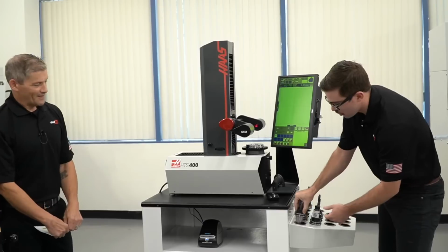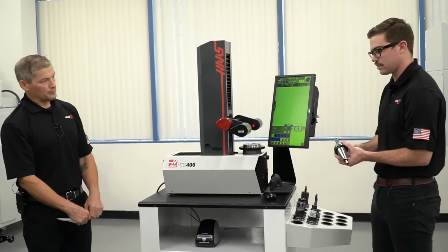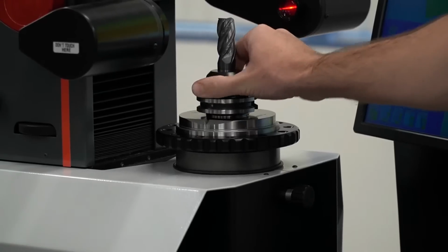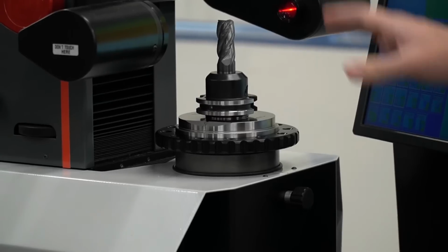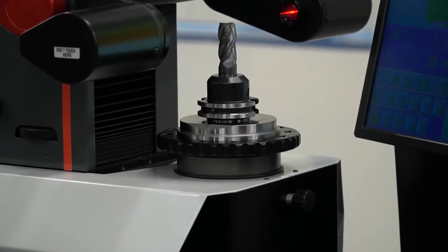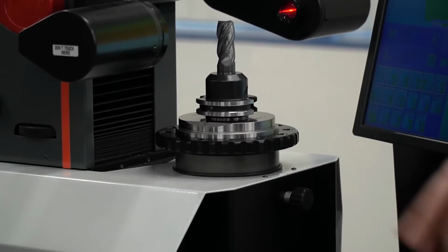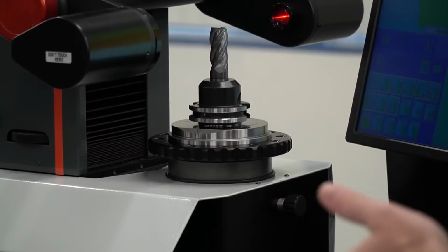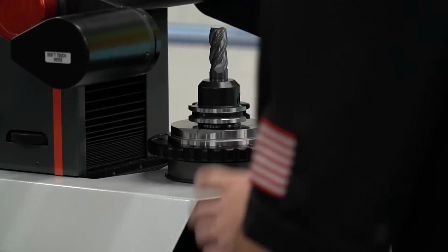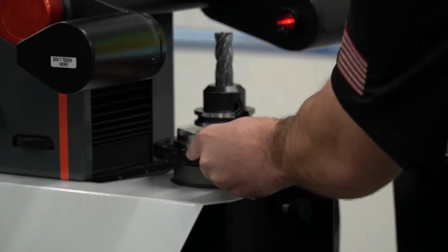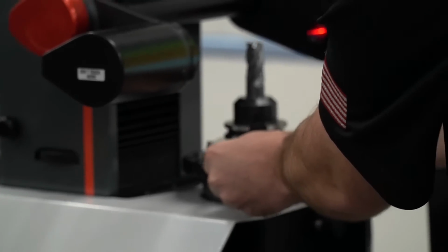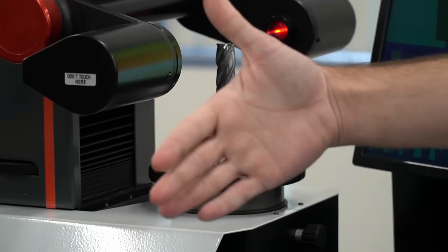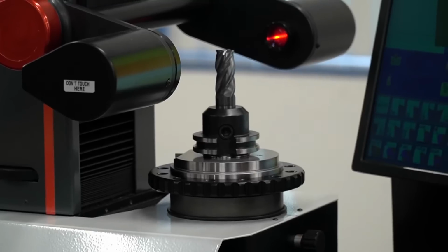Yeah, so you start by grabbing whatever tool you need. In this case, this is going to be a 3/4 inch CAT 40 end mill with 4 flutes. I just drop it down right here into my tool sleeve. So it just sits in there with gravity, right? Yep, and when you calibrate it, it makes sure that you have cleaned everything. Exactly. No dust. Sometimes you have dust, you just clean off the top, and that's really easy. So once it's set in there, you want to rotate the tool while it's in there. What this does is it allows you to set the largest Z height, which is going to be the length of your tool, as well as the X diameter height.